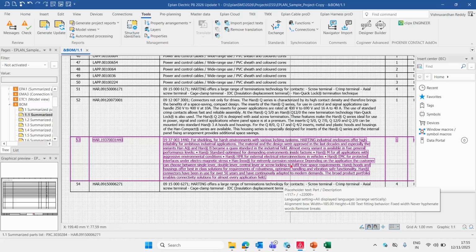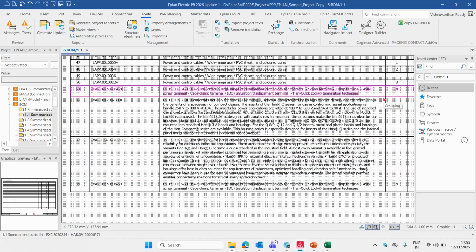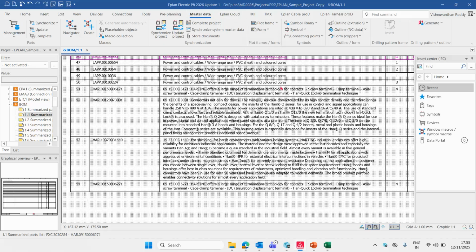By understanding this, tomorrow if you want to add any parameter, I don't think it will be a bigger challenge for you. All you have to focus on, when you add any parameter, is the data area box, which is very, very important. If you don't put the data area box properly, sometimes the boxes will not come correctly, sometimes the text will not come correctly. Those problems will always happen. So how to check: right click on that particular box and select associated objects. That will tell you how exactly that form is done.